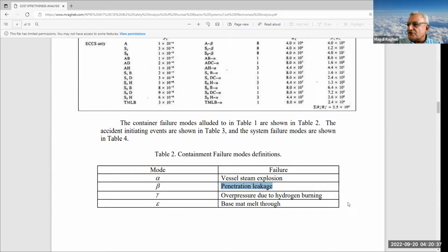So in that case, radioactivity leaks with the steam under pressure, and that happens at, say, conduits that you have for the cable for the instrumentations, as well as cable, and piping that brings in the feed water heater to the steam generator, and the piping that carries the steam out from the reactor to the steam turbine.